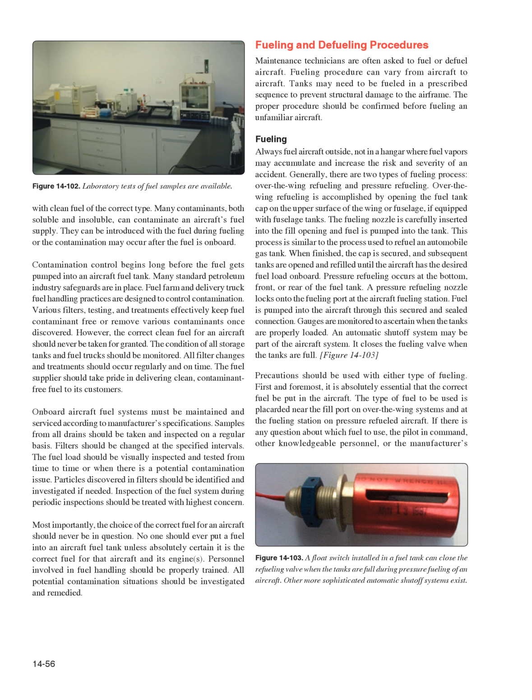Fueling and defueling procedures. Maintenance technicians are often asked to fuel or defuel aircraft. Fueling procedure can vary from aircraft to aircraft. Tanks may need to be fueled in a prescribed sequence to prevent structural damage to the airframe. The proper procedure should be confirmed before fueling an unfamiliar aircraft.